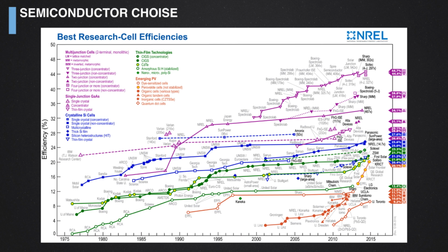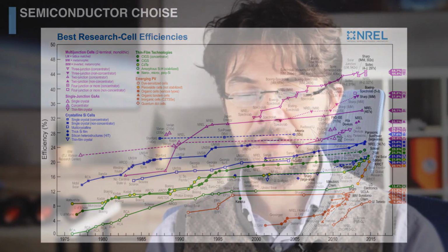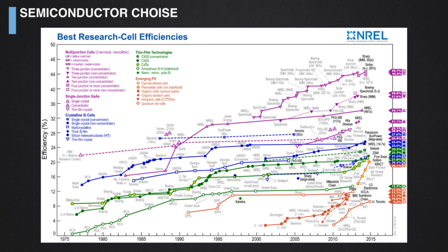But year after year, researchers found new means of producing energy through different materials. So you will see that nowadays we have the thin film technology that involves very complicated compositions, like for example the so-called CIGS materials, which means copper, indium, gallium, selenide. Another possibility is that of using cadmium telluride, which is another binary compound, a little bit environmentally unfriendly.